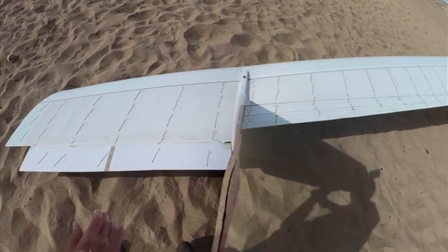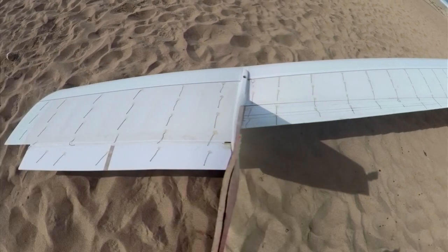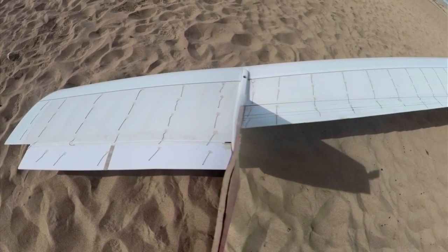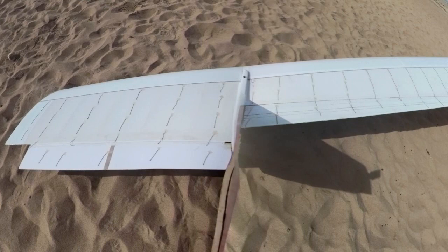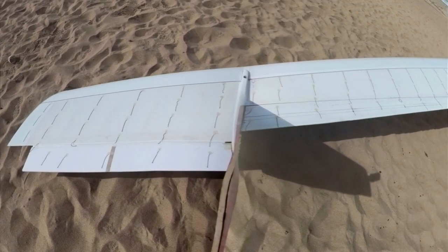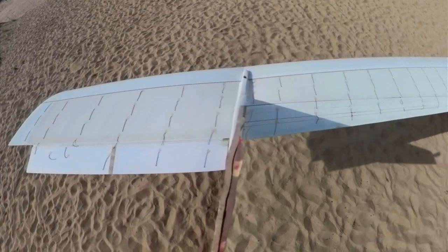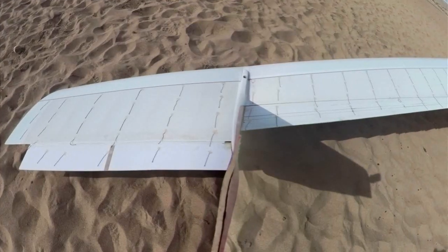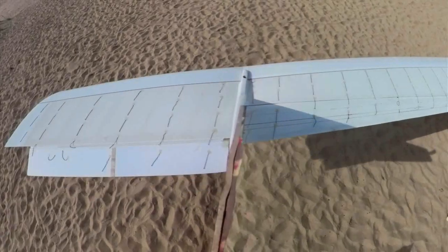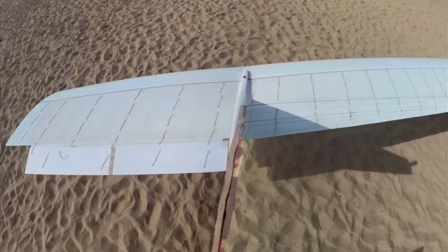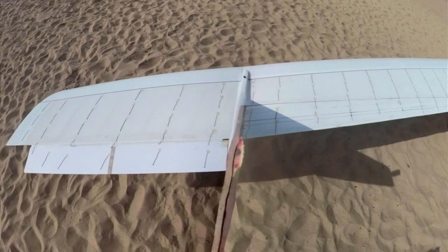Inboard and outboard, the flow looks great. Elevons go up, elevons go down. Everything's pretty well behaved. My buddy Dave had to come out and unstick some of the tufts. So there's some up elevon applied. Here I come in. There's some down. Flow still attached. The tip starts to go a little bit spooky right there.